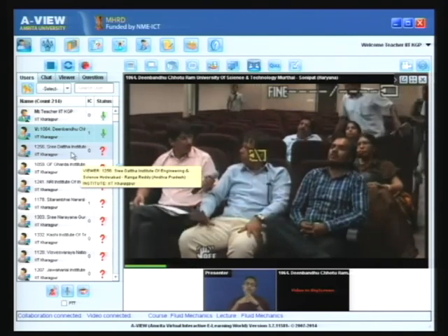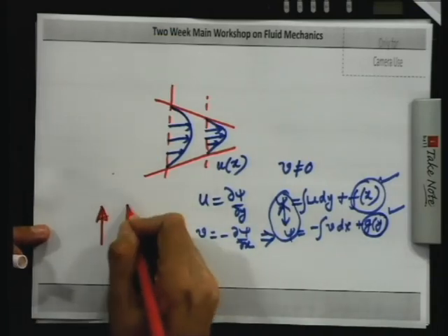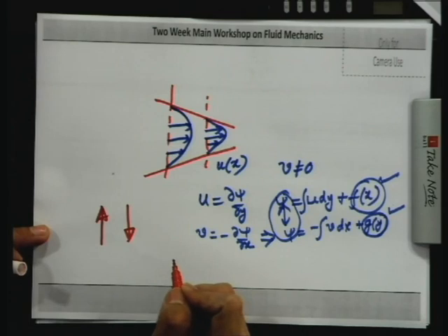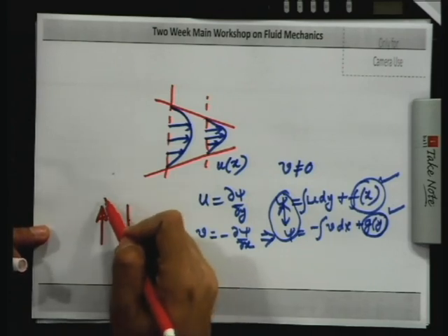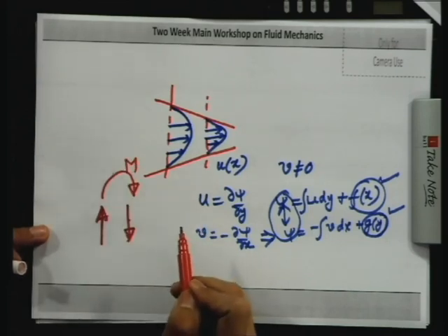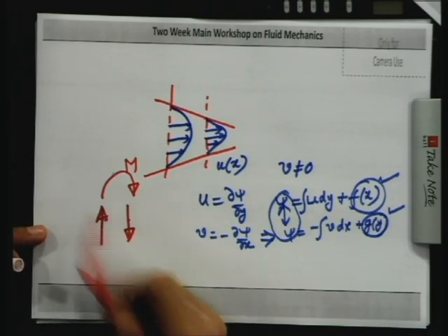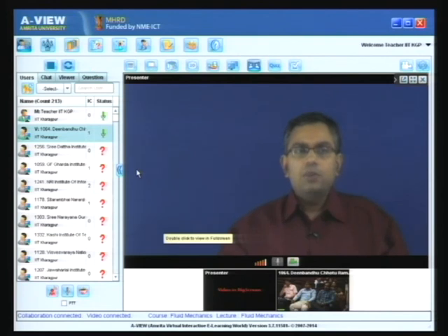You can understand a couple like this: if you have two forces which are equal and opposite, they actually form a moment. This forms a moment M, which is called the couple moment. Just like body force, if such couples are present within the volume of a fluid, that is called a body couple. Normally fluids will not be able to sustain these body couples, but if there are particulate matters within the fluid, they may sustain these body couples.